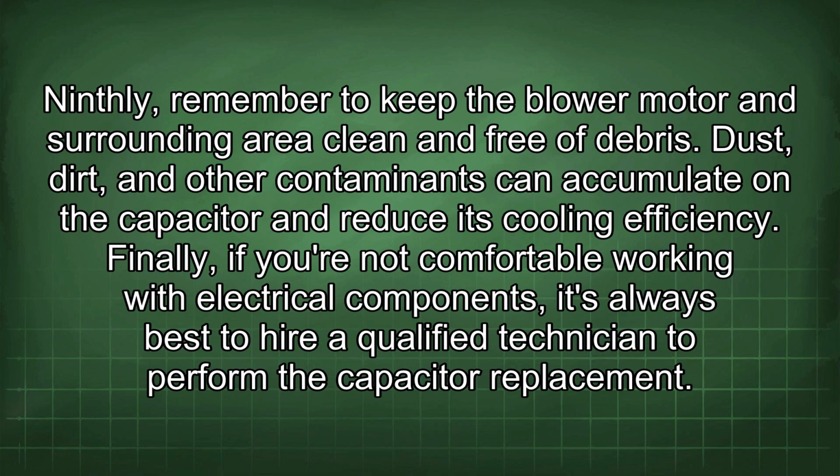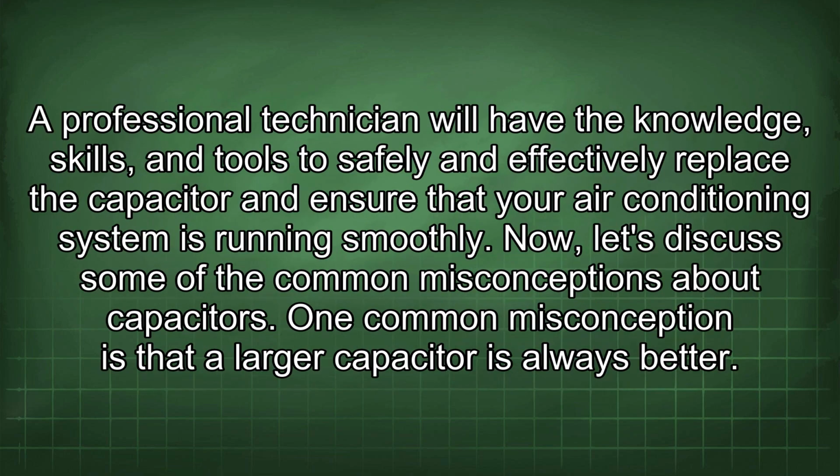Ninthly, remember to keep the blower motor and surrounding area clean and free of debris. Dust, dirt, and other contaminants can accumulate on the capacitor and reduce its cooling efficiency. Finally, if you're not comfortable working with electrical components, it's always best to hire a qualified technician to perform the capacitor replacement. A professional technician will have the knowledge, skills, and tools to safely and effectively replace the capacitor and ensure that your air conditioning system is running smoothly.